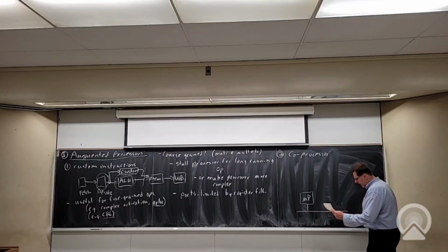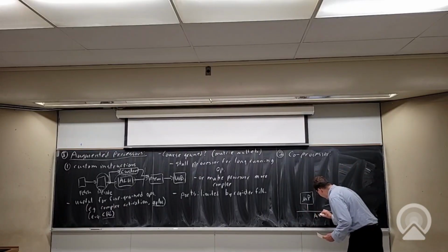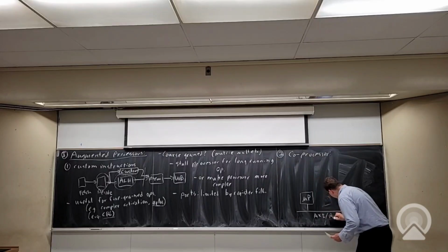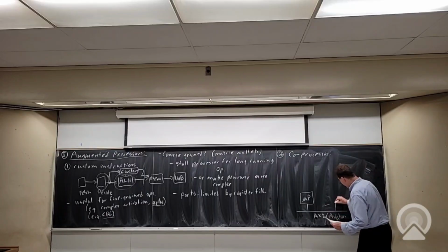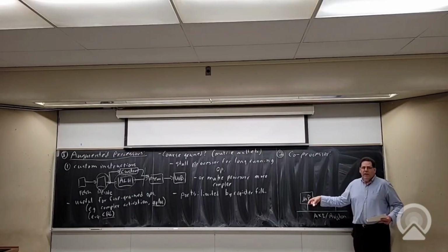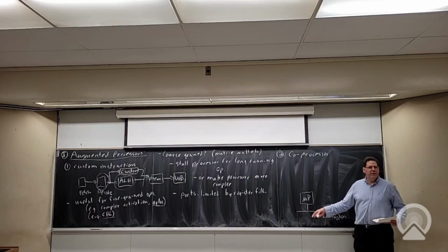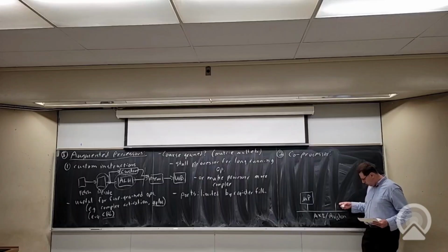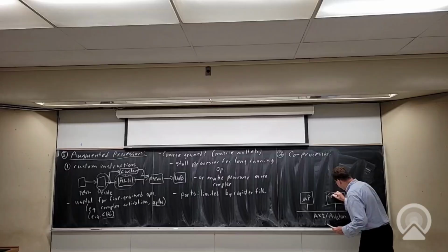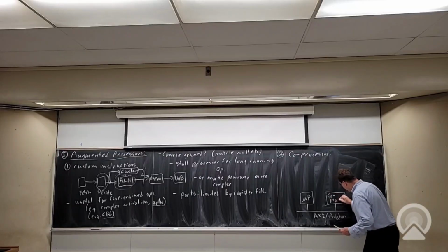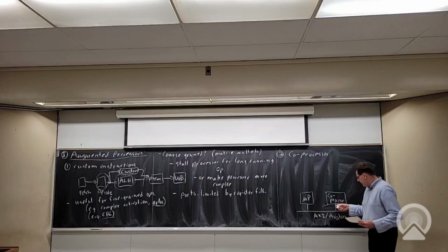using a standard bus. Okay, so it could be AXI. That's the most common one now. Altera also has an alternative called Avalon. And we can basically send commands over this bus, right? For example, this could be a memory mapped bus where we read and write from certain addresses to send commands to a peripheral. So we can make a coprocessor, so a block of logic that also has an AXI interface.